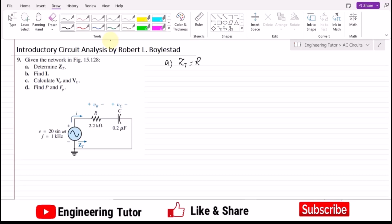After it, we look for the reactive elements present in our circuit. There is only one reactive element, the capacitor. For any capacitor, I have to write a negative sign with the j, and after it write the capacitive reactance.